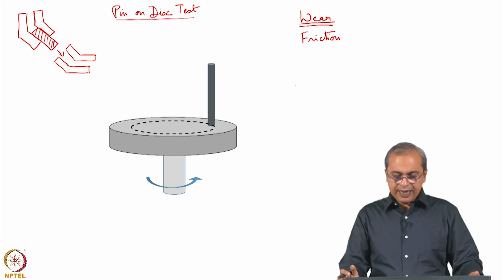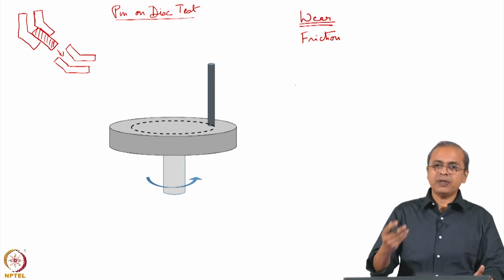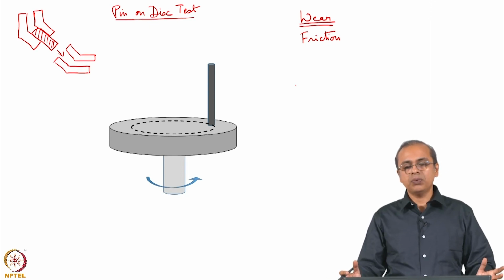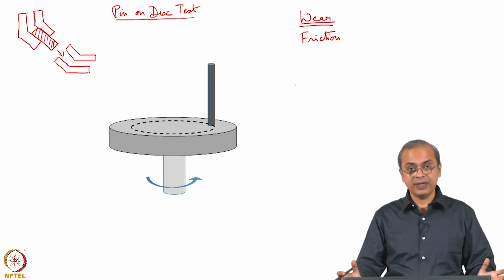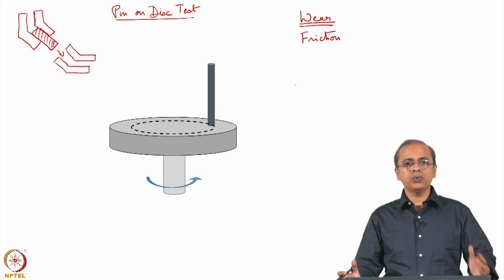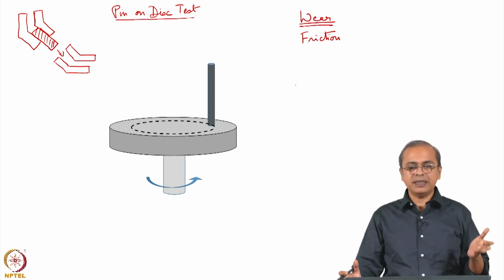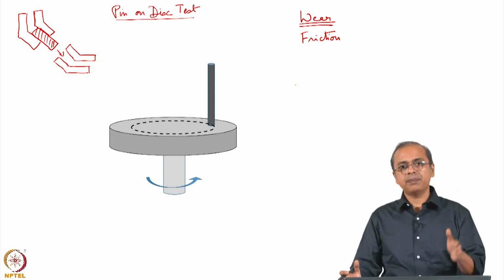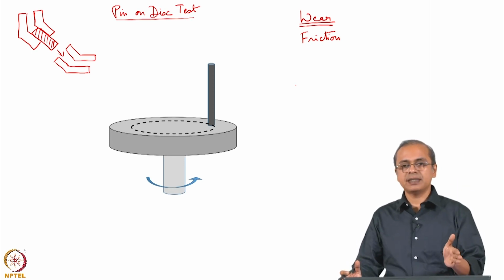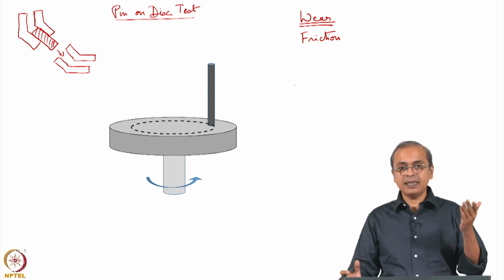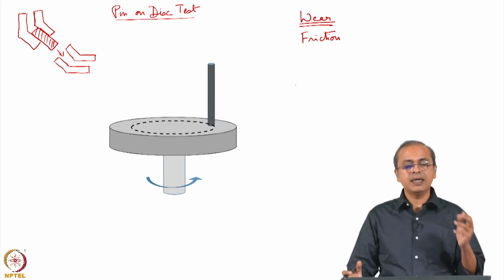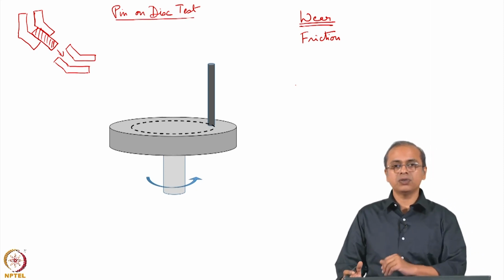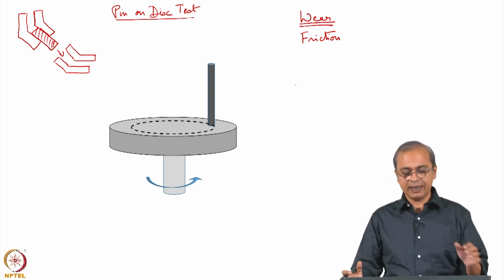To do the wear test, basically you have to create the same situation of friction, and see how that sample behaves once it is subject to friction, in some kind of controlled manner. That is basically what a test is, right. So, you have to set it up so that you can test one sample, and then test some modification of that sample or some other sample, and then compare results. The conditions should be reproducible, and there are some defined conditions for it.